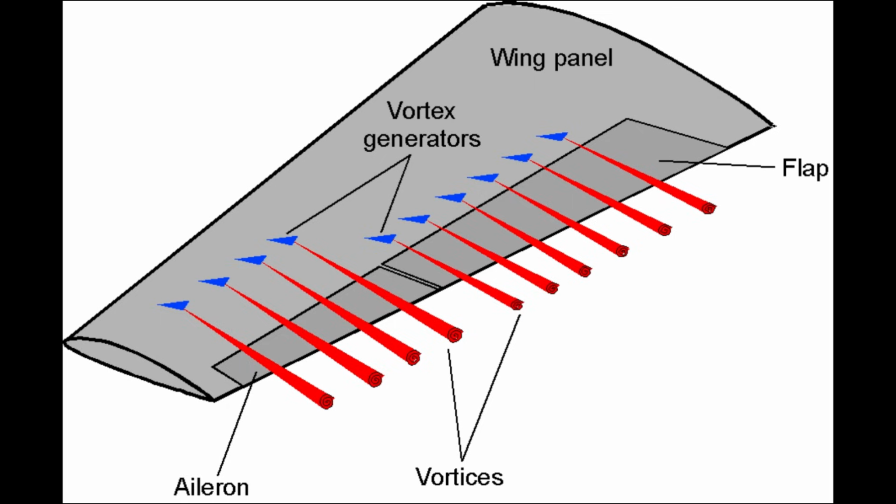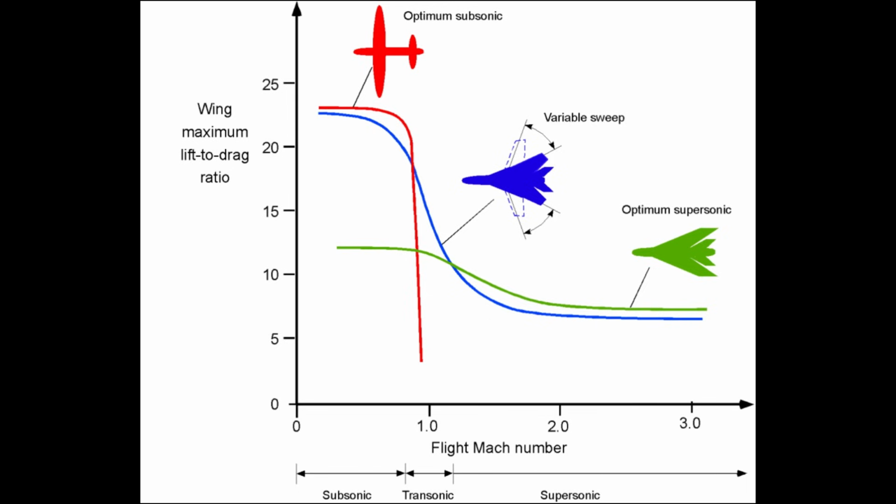Importantly, the swept wing did not eliminate all aerodynamic challenges, it shifted them. Sweep introduced new issues at low speed, including reduced lift coefficient, higher stall speed, and more complex stall behavior. Takeoff and landing distances increased. Aircraft required higher approach speeds and more careful handling near stall.